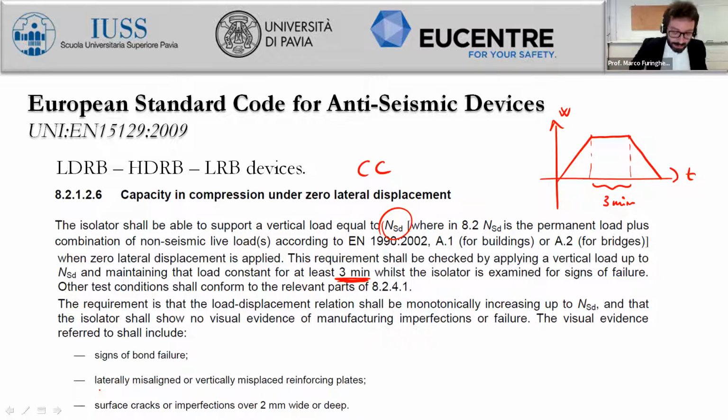Generally, there is a gap between the restraining vertical part of the equipment and the bearing. The operator allows the equipment to go up in displacement control. As he sees that the vertical load starts to increase, he switches from displacement control to force control, and then applies this signal.